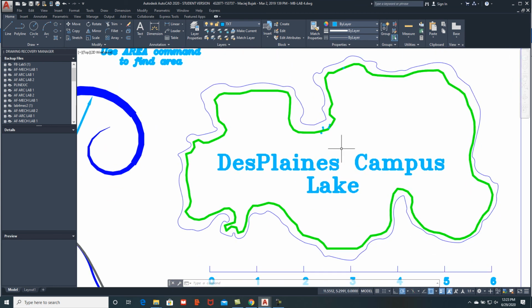The display is linked with the sketch command, and so you can use the sketch command, sketch, enter, and then when you click, you have to be careful because that's what puts the pencil down, and wherever you move the mouse, the pencil stays down.